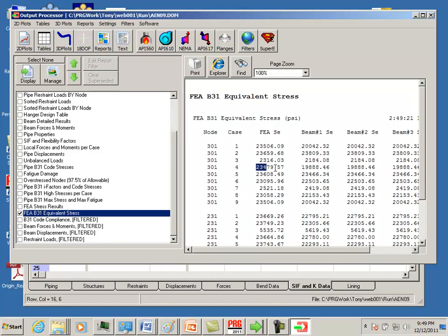And now we see that the stress cases align. So if we want to include pressure as a stress intensification factor for our sustained and occasional stress analyses, we will be comparing to membrane plus bending stresses from a finite element model.